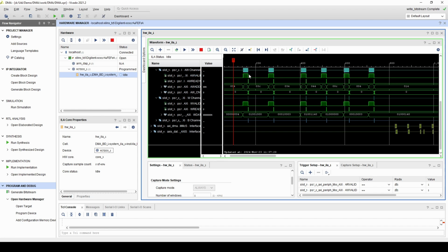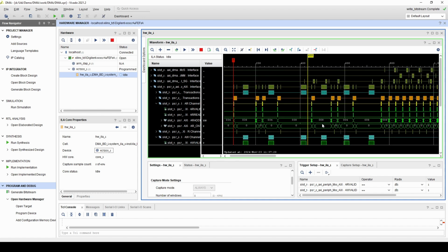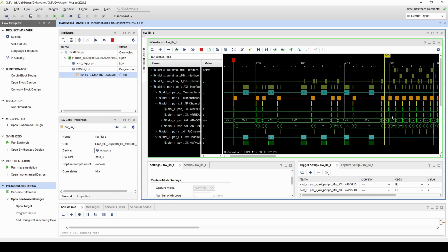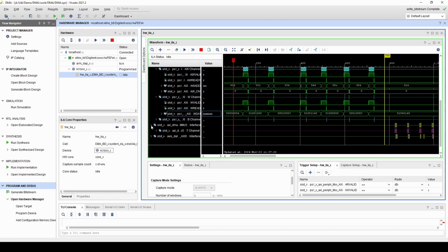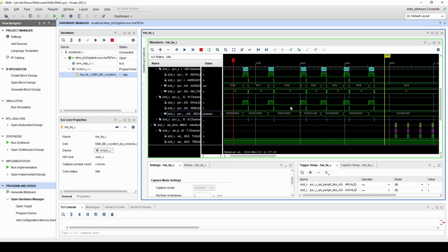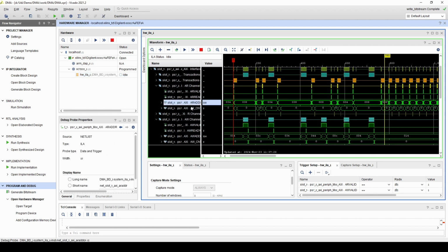Here we see the configuration of the RX. The first BD ring, the enable, and the last BD ring. In this place the RX is ready, but the TX didn't generate any data yet. So we generate the first BD for the TX, the enable, and the last one, and the DMA starts working, and the data is coming out and gathered in.